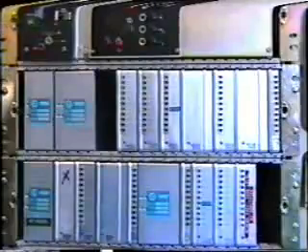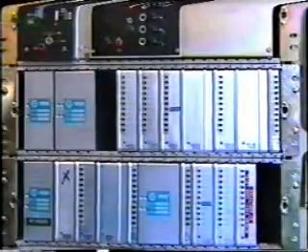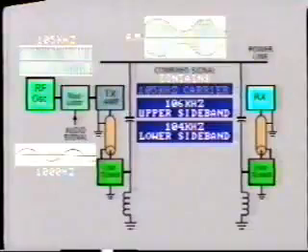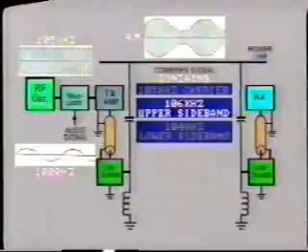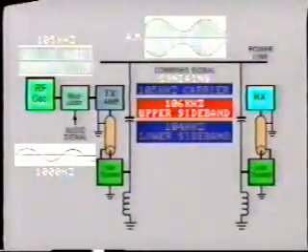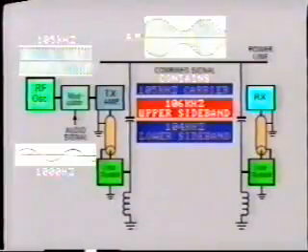Other people asked that same question and came up with the single sideband system. Here, both the carrier signal and the lower sideband signal are suppressed in the transmitter, and only the upper sideband frequency is transmitted, 106 kilohertz in our example. The advantage is that it requires much less power to transmit the signal. And for this reason, portable communications equipment is usually single sideband, as there is a considerable saving in weight and size.